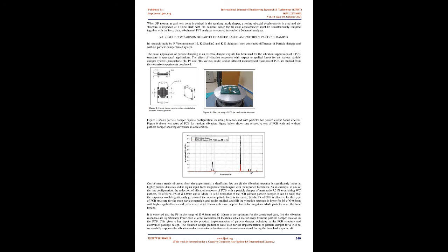1. An impact hammer with a load cell attached to its head to measure the input force. 2. An accelerometer to measure the response acceleration at a fixed point and direction. 3. A 2 or 4 channel FFT Analyzer to compute FRFs. 4. Post-processing modal software for identifying modal parameters and displaying the mode shapes in animation.